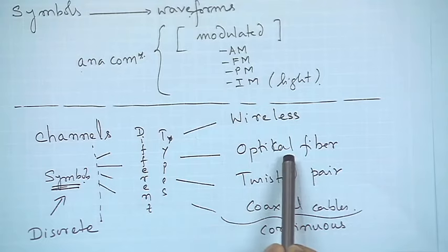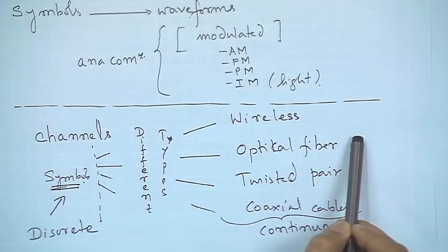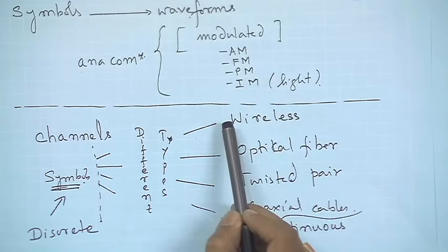Beyond that, as we talked about these channels earlier, each channel is unique in its own way. So when we send the same bits 0 1 0 1 0 0 across a wireless channel or the same sequence over an optical fiber channel, the chances that the sequence 0 1 0 1 0 0 is going to remain the same in these two different channels are very low. They have to be very, very different. Now that depends upon the channel properties, which includes the amount of noise in the system. Usually we ascribe noise to the amount of noise at the receiver. So basically when we talk about channels, it's the amount of distortion that these channels bring in. So there needs to be equalization of the effects of the channel. So first the channel needs to be estimated, followed by equalization of the channel.